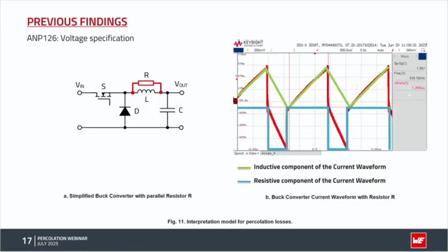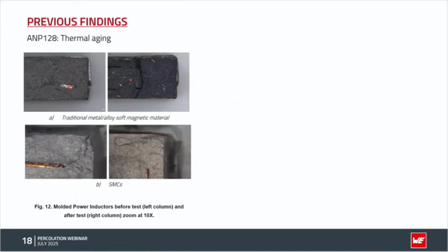So at this point, let us imagine what is going to happen with our design if we add a resistor in parallel to our power inductor. That is the open question for you. Why? Because normally we say that this resistor is so high. We are speaking about thousands, hundreds of thousands of ohms. But in this case, it's going to decrease to around some milliohms, and that is just like a short circuit. That is the effect.